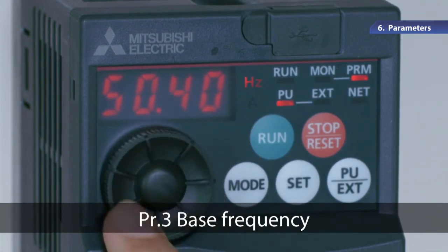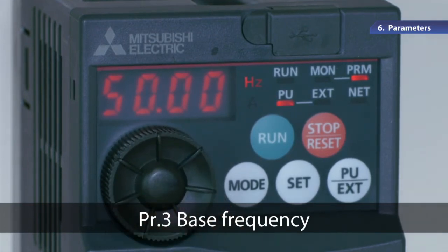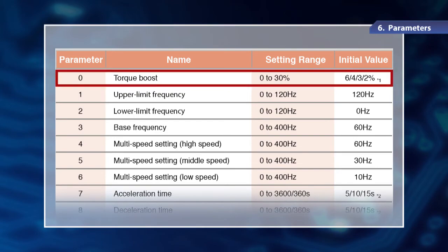If not changed, the voltage drops too much and it leads to insufficient torque. Torque is force that rotates the motor. As a result, the inverter may stop functioning due to an overload. There is another parameter important for torque.